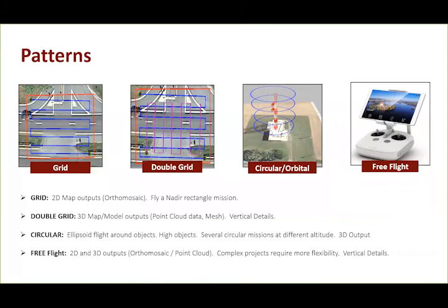Anything from orthomosaic TIFF files that have been rectified and come into scale into an application, or again working with the point cloud where you get the XYZ, also the RGB values from the photographs, and to plot virtual survey data to create an environment within a CAD program or a simulation program where you're able to render an animation on the surface of the point cloud.